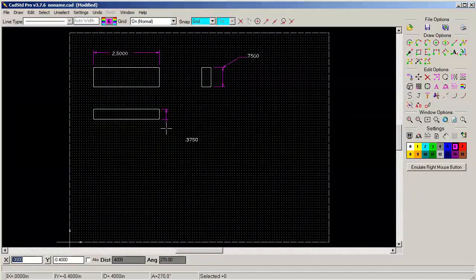Not shown, but you should select white layer 0, then click Draw, Text, and place front view, side view, and top view right next to each view. This is important if you plan to give this print to someone. Now save your file.